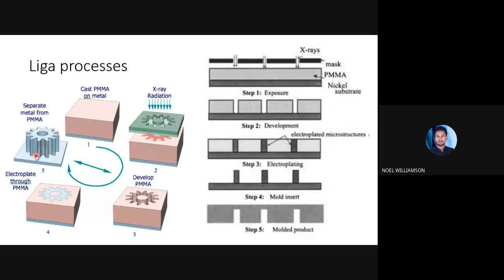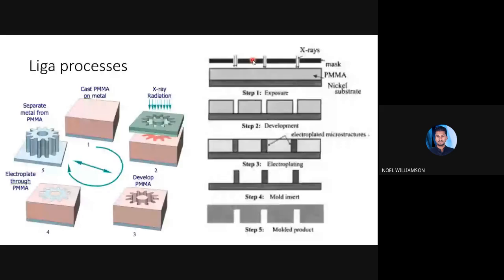Now in another case where we want a mold, suppose in order to create a structure like this, we want to have a mold like the pink one with some other material. Suppose we need to have a mold, then we will do like this. That is, first of all, we are creating the same step. That is, the metal is being here, above which the PMMA is cast.